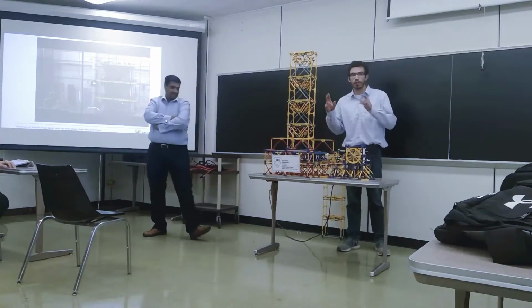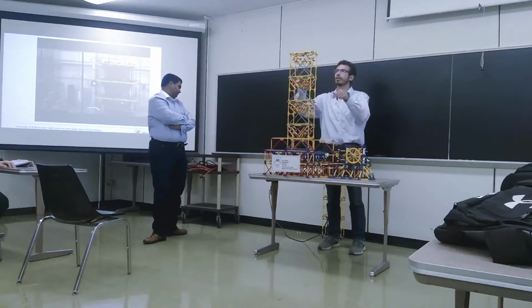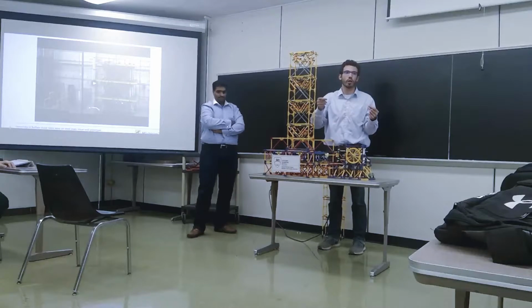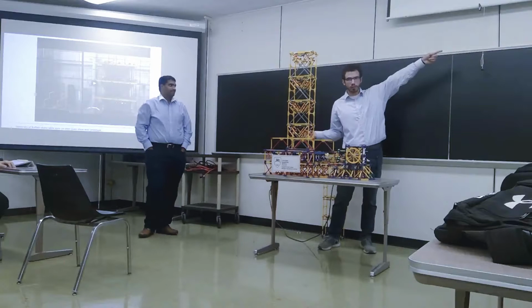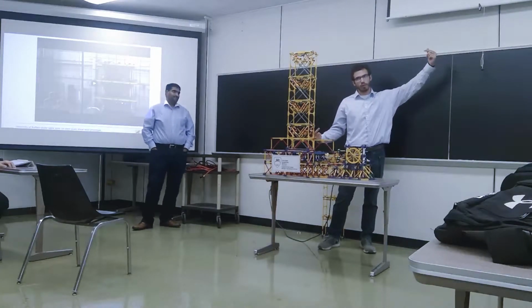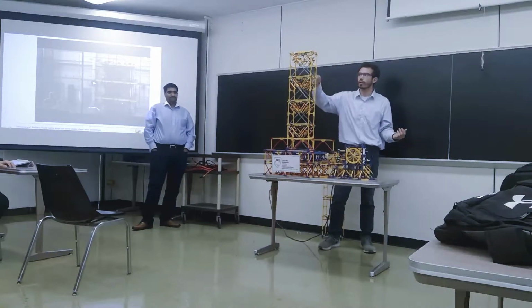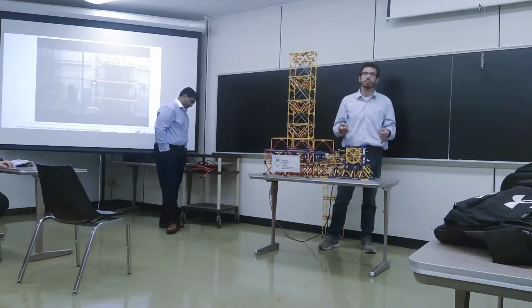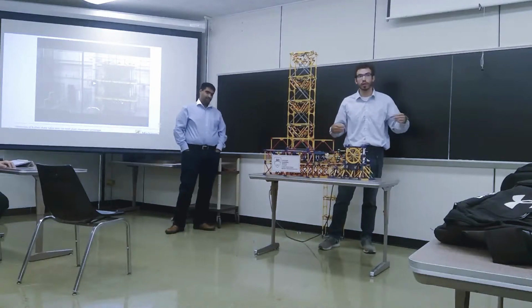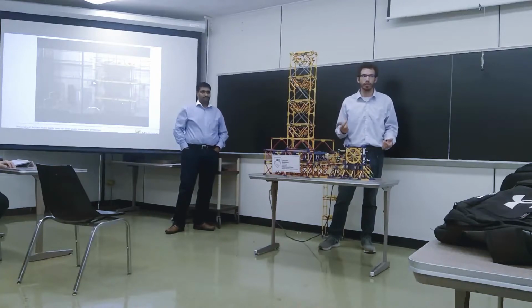Now I'm going to talk about this. Here's this different building. As you can see, it's braced. So it has these X braces in here. I designed these braces so that they're tension only, which is very common within buildings. So if you have just a long brace that's supporting something, if you apply compression load to it and you don't have any bracing on that brace, it'll buckle. So usually when you're doing bracing like this in a structure, you assume that it has no tension or no compression capacity. However, braces also yield. So braces elongate if they get to the yield zone. And yielding is the way that buildings dissipate energy during earthquakes.